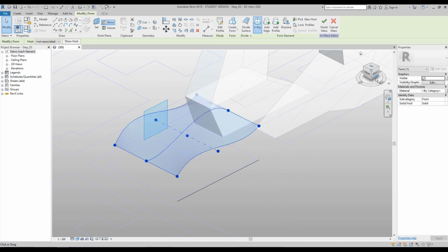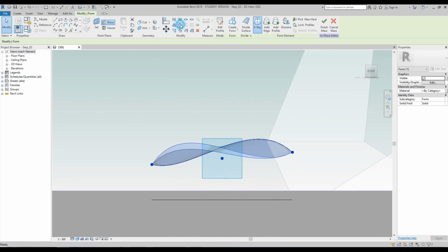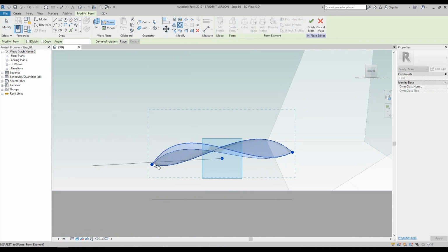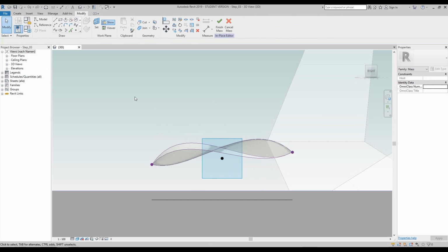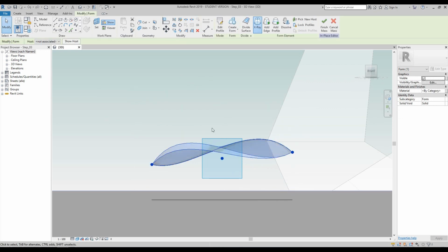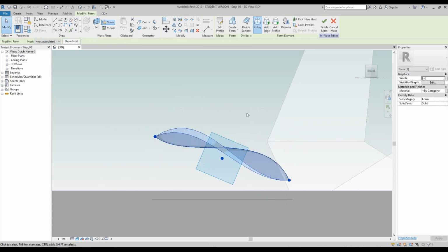we can rotate it. So if we go to the right side of the view cube and then press the rotate tool button, and pretty much if we use the left hand side, rotate it up to about 30 degrees. Actually, that's a bit too high, so undo that. Let's rotate the whole thing again, select it all, and rotate it to approximately 23 degrees. So it's a bit like that.